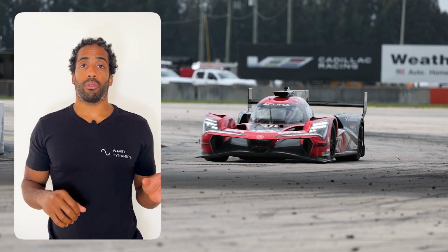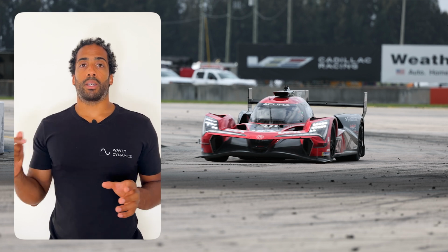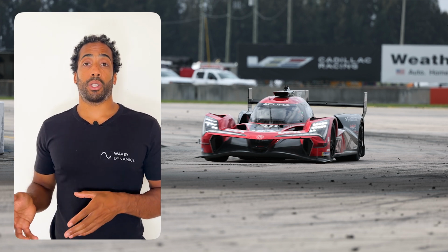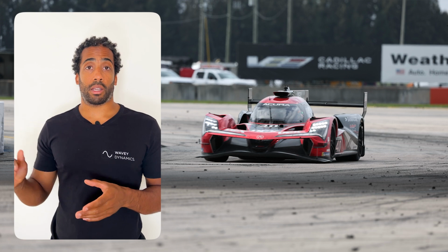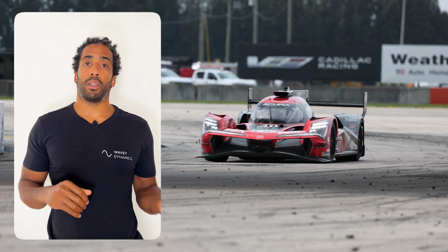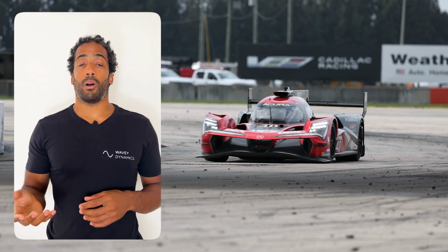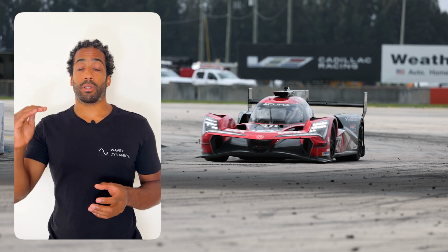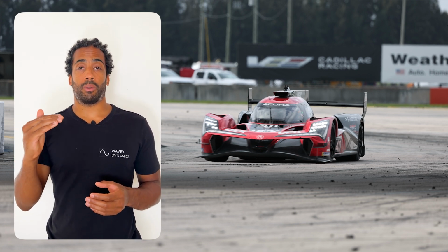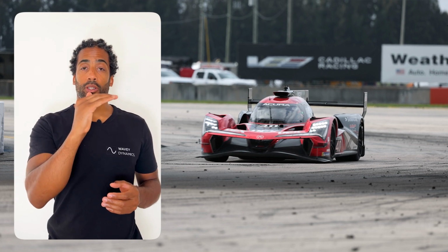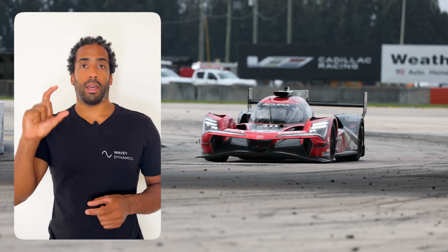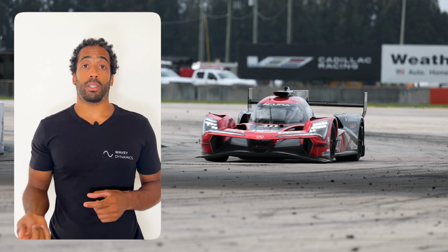One with a high natural frequency, one with a lower natural frequency. The higher natural frequency, the higher spring rate, is going to give a higher variation in contact patch pressure as it goes around the track and travels over bumps than the car with the lower natural frequency. So I can see that with the prototype cars, every time it goes over the bumps with the higher natural frequency, all these body accelerations are causing sharp spikes and rises and falls in the contact patch pressure.